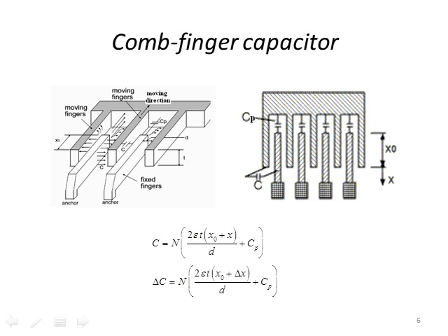And you can look at this on your own to derive this change in capacitance delta C. And remember here, N is the number of fingers that you have. Now, I'll show an example in a minute about why this is important. These comb finger capacitors can be made using microfabrication techniques, and most of the accelerometers that are in cars today are based on these comb finger capacitors, which are moving structures.